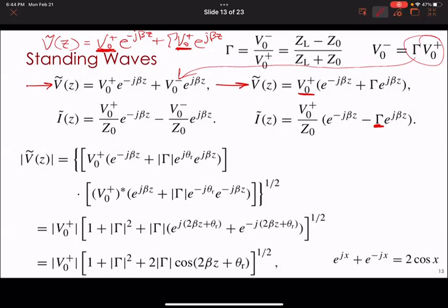At 2.45 gigahertz. It injects it in there, and your microwave oven is a metallic cavity. That's why, when you look through the door, you see a whole bunch of little holes, but mostly it's metal. It's a screen. Those holes are much smaller than the wavelength of the signal. That's what gives it some shielding effectiveness.